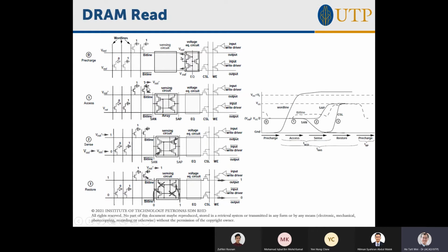And the opposite will happen if this is logic 0 here. This is logic 1, so this transistor will turn on and will rapidly discharge this line. Then this line is logic 1 now, and it will rapidly turn on this one, and then it will discharge this to logic 0.